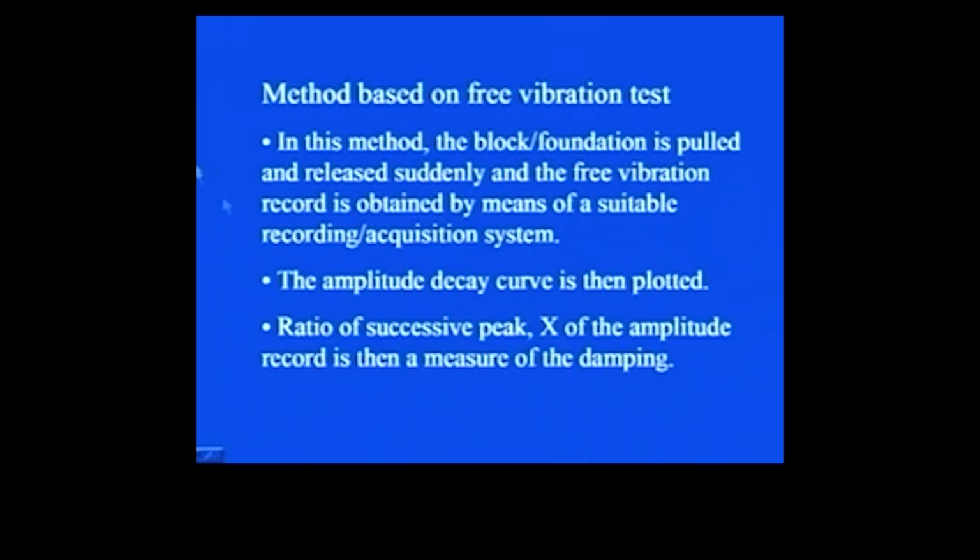So once this block or foundation has been displaced, it will vibrate under the forces inherent in it. Under those forces the amplitude of the system will go on decreasing with time. So that amplitude decay curve can be plotted because a suitable measure has already been provided to record this amplitude.